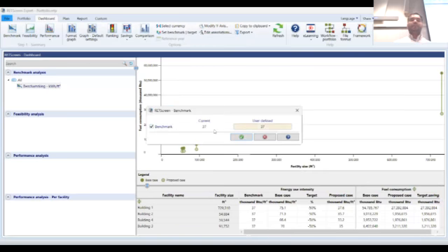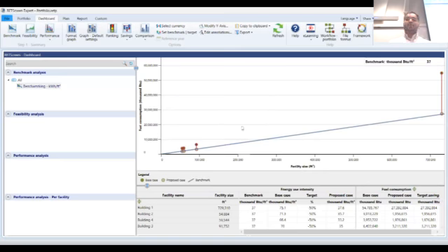So I'm assuming for residential property in Washington, DC, they need to have at least 37 kBTU per square foot in order to comply with BEPS, right? So that is the graph that I plotted. All the plots that are above this graph are not complying with BEPS right now. If you see any data point that is below this, it is complying with the BEPS requirement. So right now for our case study, none of the 4 properties are complying with BEPS.